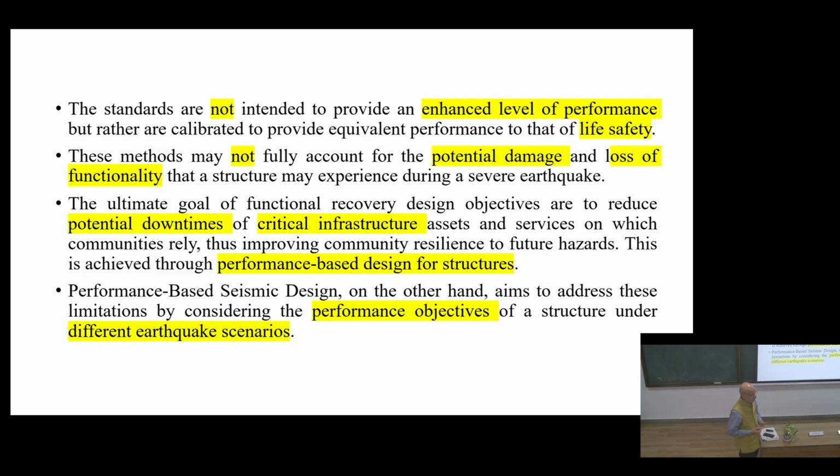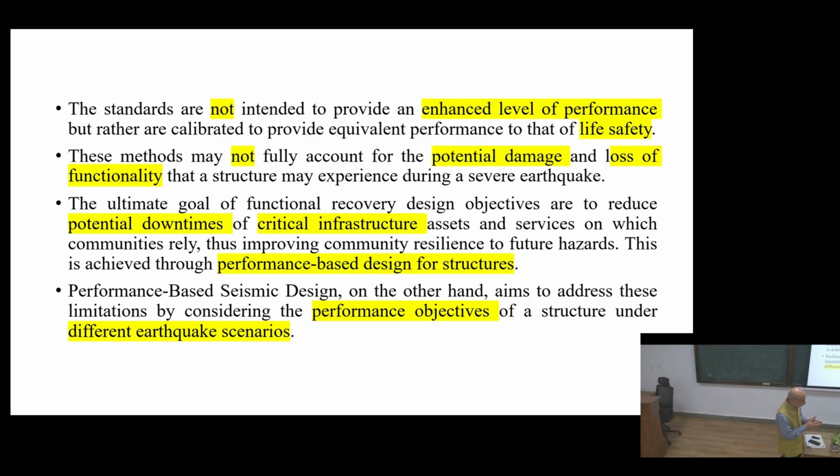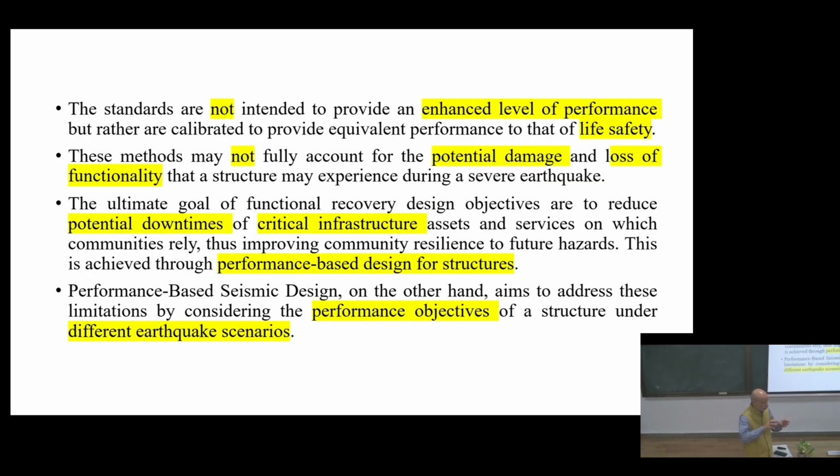Those parameters you take into account: the ground motion which is expected, and according to your design, how much is linear deformation, how much non-linear deformation, and at what location in the structure this deformation or displacement is coming in the picture. As Professor Dattara said, those are the places where we understand the formation of the plastic hinge. So the difference between the mechanical hinge and plastic hinge is well understood by all of you, I believe.